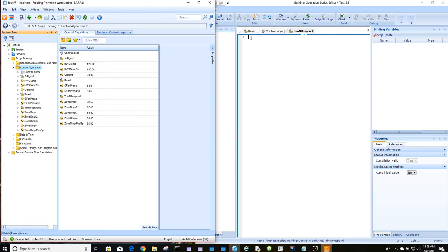There's a mapping between two values or two schedules of values in order to create an output that's proportional to the input, basically. So it'd be used in things like outside air temperature to reset your hot water supply temp set point, or using terminal load, average terminal load for all the VAVs to reset the supply air temperature set point, things like that. They use reset blocks or reset functions or linear fit, however you want to call it, or slope intercept.